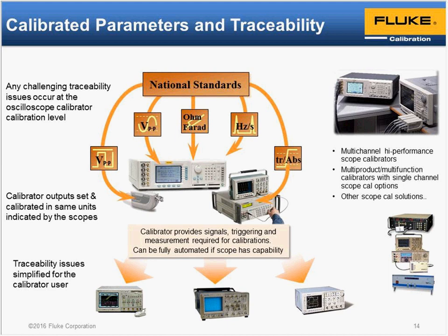High-frequency peak-to-peak voltage is a difficult parameter to measure and establish traceability for, when you have to think a little bit about the higher frequencies being an RF and microwave measurement, where the standards are always maintained in terms of power. And impedance comes into the conversion to voltage, as well as some other considerations, and that's quite tricky. Those are the sort of things we'll be exploring in the third topic in this series, which will be presented at another time. So the oscilloscope calibrator provides that vital link.